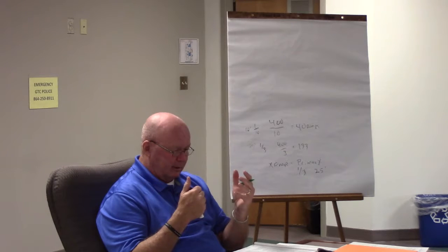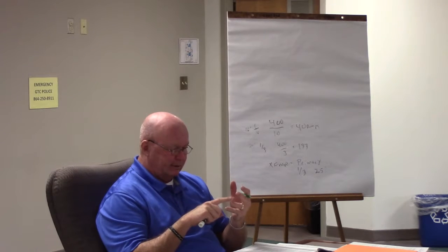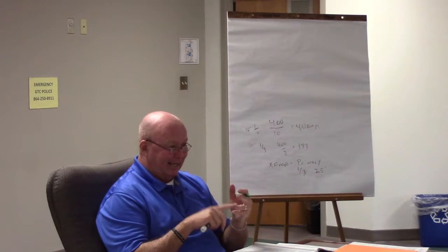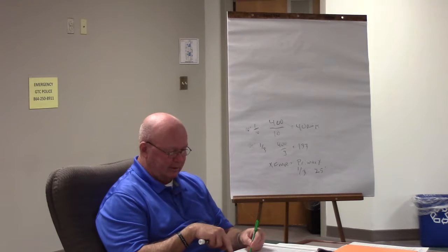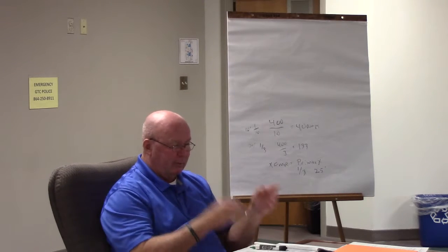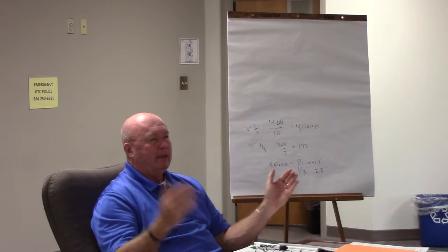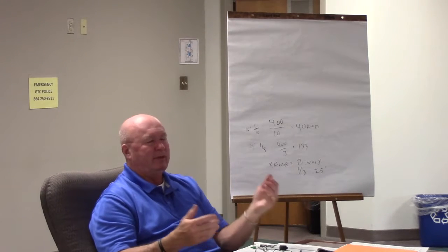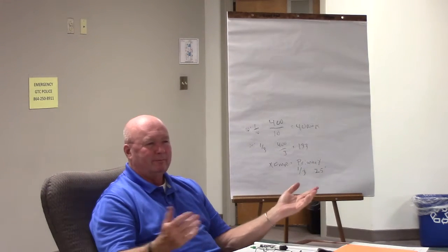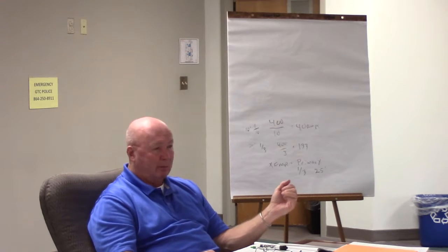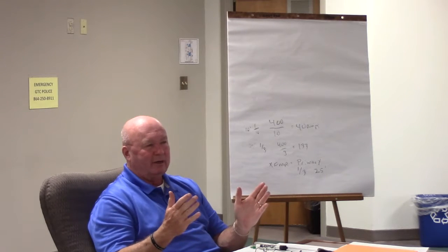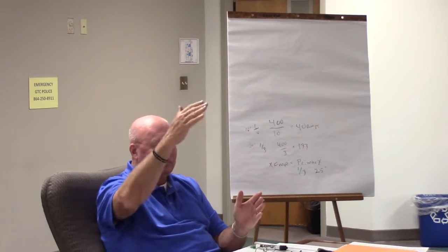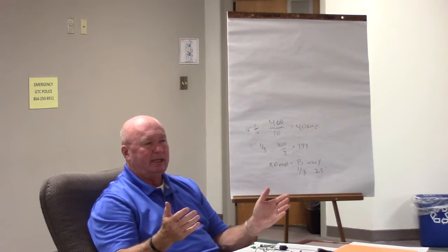All right, and bullet point number 3 says the total length of the primary, not or, but the primary and the secondary conductors must not exceed 25 foot. I think that's the key. When we're putting it in the field, what do we generally do? How much length are we talking about? How much do you use to feed your transformer? About 15 foot, maybe? Yeah, at the most. And then your secondary coming out of your transformer is generally what? Because the panel, yeah, it's what? 10 foot, let's say, at the most.